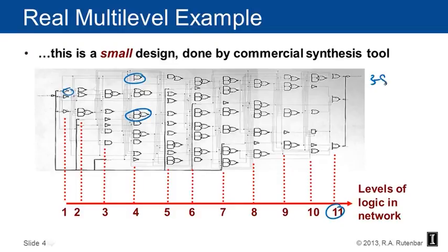This has somewhere between 3 and 8 gates per logic level, and this thing has something like about 65 gates in all. This is a pretty simple little design, but this would be really very impractical to do in a two-level form. And with modern synthesis technologies, we could specify how many levels of this logic we're actually willing to put up with depending on how fast we need it to go. So we just need some technology that's able to do things that look more like this.